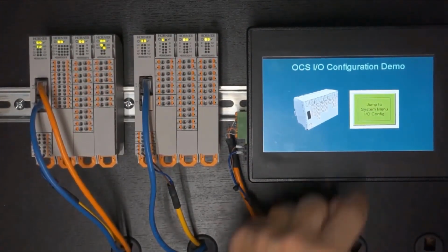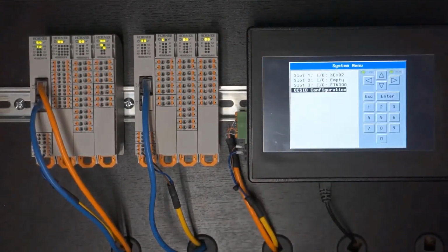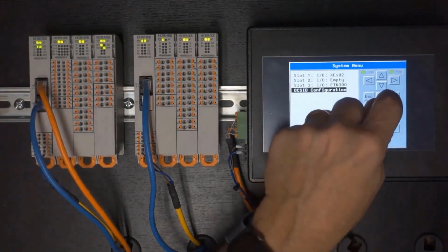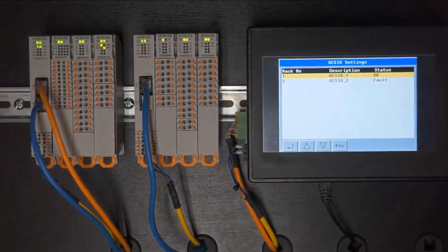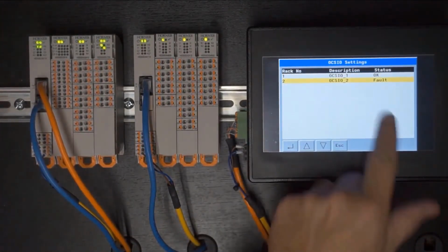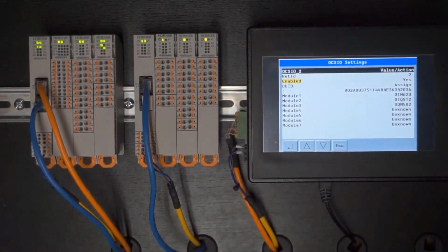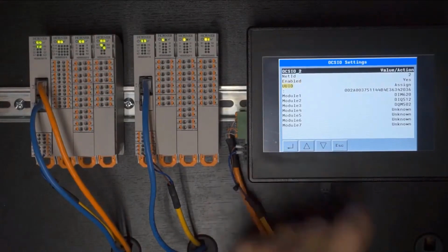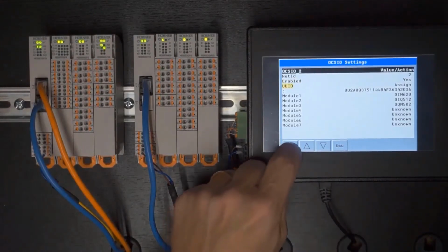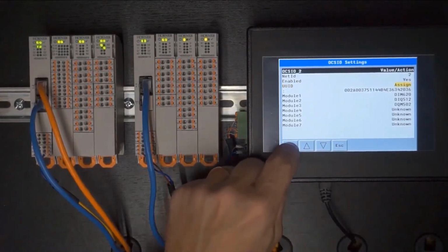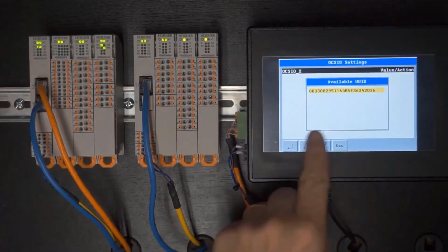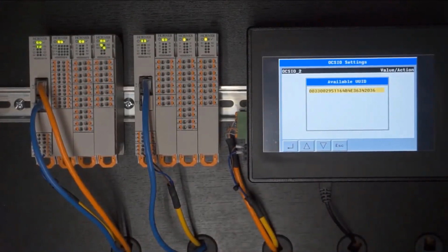So if it doesn't recover automatically, we'll see what we can do to get the system back up and running without opening Cscape. So we'll go to the system menu and we have the shortcut here. We'll go to the OCS-IO configuration and go to rack 2 because that's the one that's faulted and the one we want to replace. Press enter. Now we're going to go down to UUID assigned and press enter again. It says that it found a new UUID and we press enter and then it is assigned. We have that new UUID going now. And if you look here, we are fully up and running.